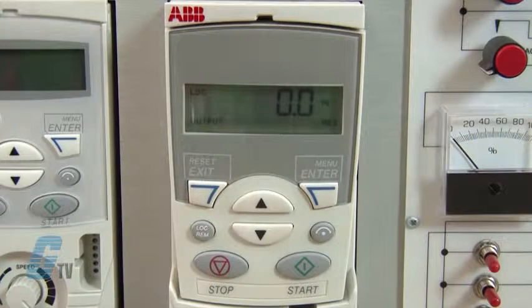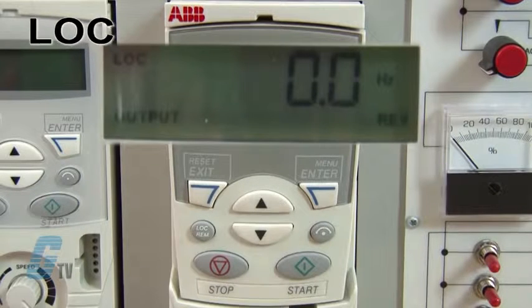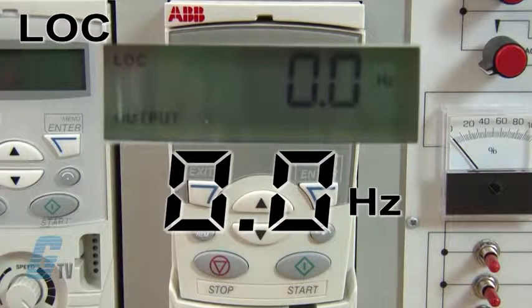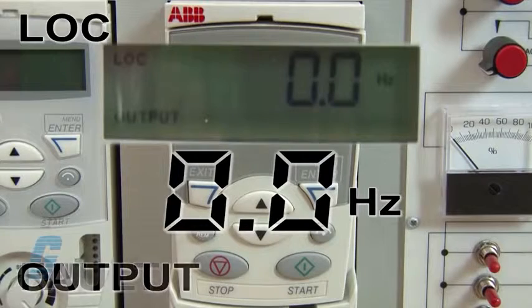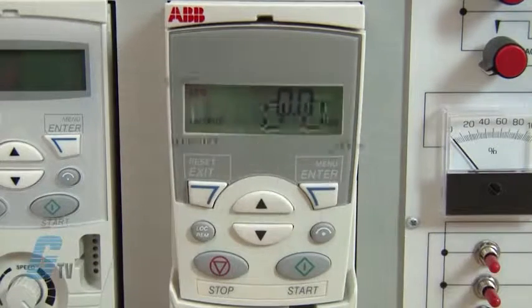The basic control panel has a single LCD line display and is divided into 5 areas. The upper left indicates the control location with either local or remote. The center shows the value or parameter with the unit of this value displayed in the upper right. The lower left corner shows the panel operation state. This could display output mode, parameter mode, main menu, or fault. Finally, the bottom right indicates the direction and status of the motor.